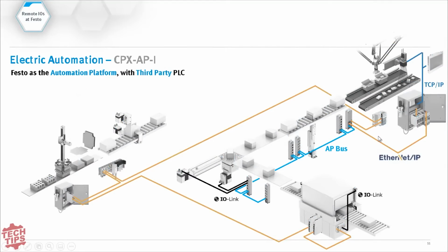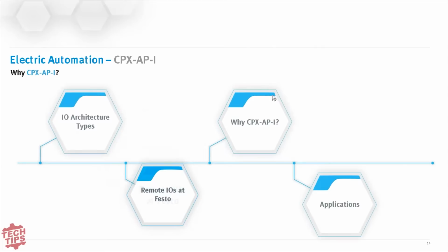Now, if we keep going, we see that now I have the same architecture, but being driven over EtherNet/IP. If I keep going further, now it's PROFINET, and then it's going to be Modbus. Why am I showing different field buses? It's because we are experiencing this, right? Machine builders usually are tasked with building maybe the same machine over and over again, but depending on who the end user is, the end user might have a different standard for field bus communication.